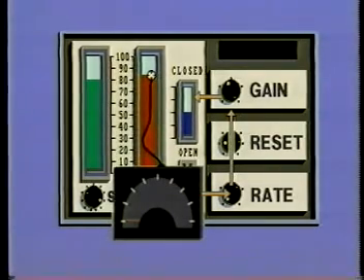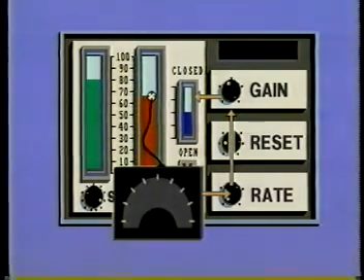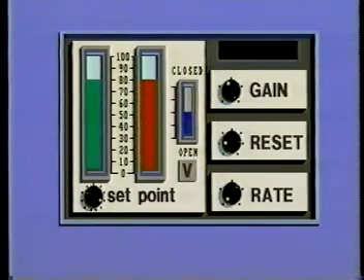When the needle indicates a fast temperature change, it adds a signal to that of the proportional unit, so additional valve motion results. But when the temperature is steady and the needle is at zero, the derivative action stops. Let's see how this extra valve movement comes about in the chemical plant.